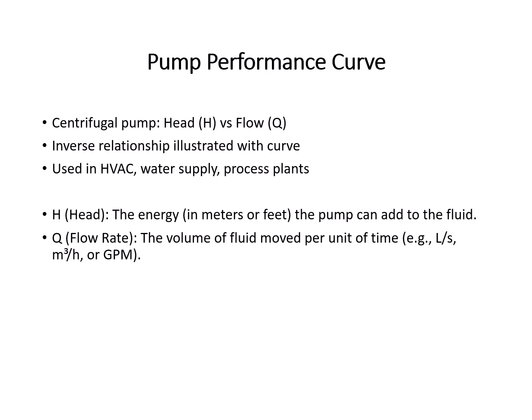Pump performance curve. Let's start with the heartbeat of a centrifugal pump, which is the HQ curve. The relationship between the head and the Q is an inverse relationship which is illustrated with a curve. When we say inverse relationship, we mean that as the flow increases, the head decreases and vice versa.